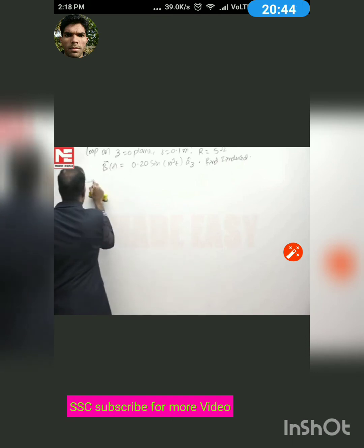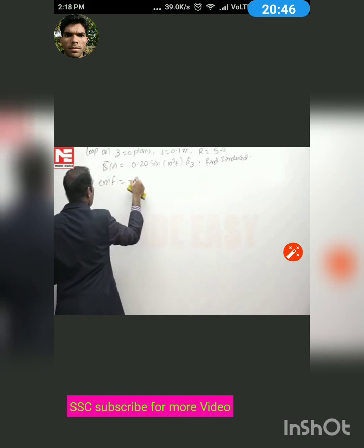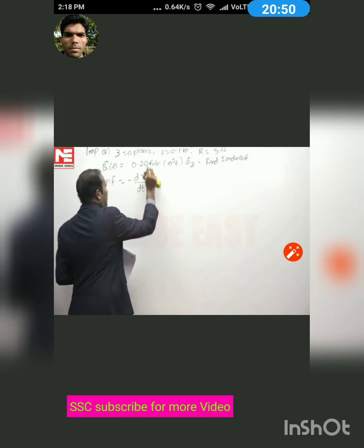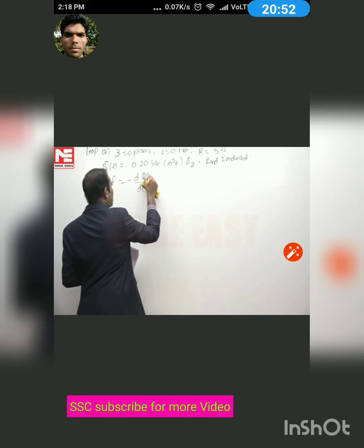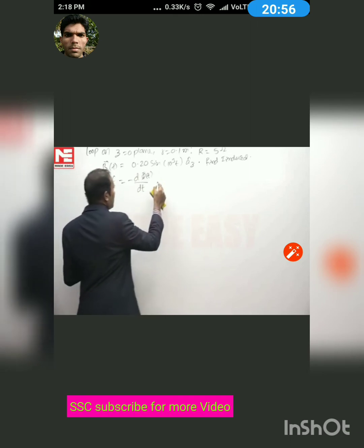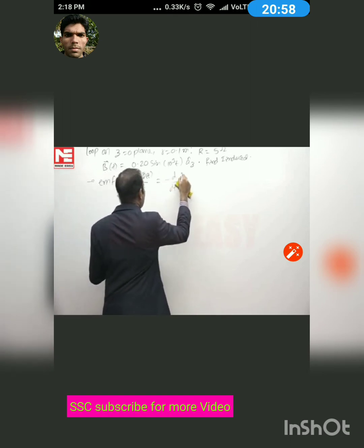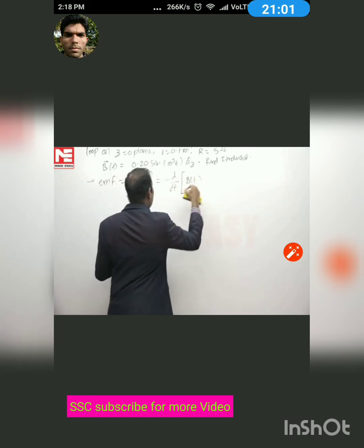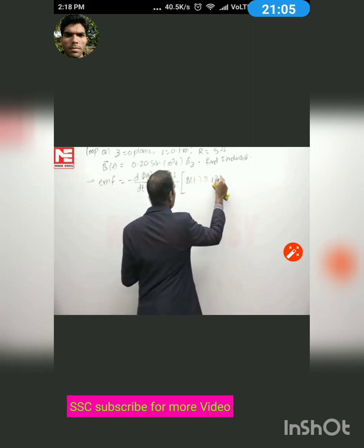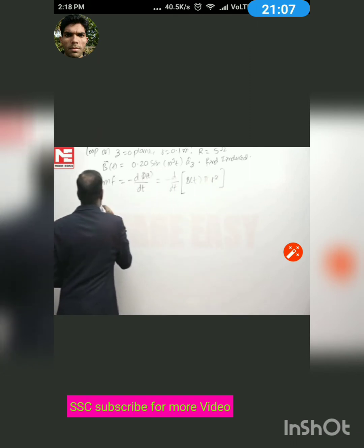So you know that EMF is minus dψ/dt, the derivative of the magnetic flux. That is minus d/dt of B(t) into the area of the loop, which is pi r squared.